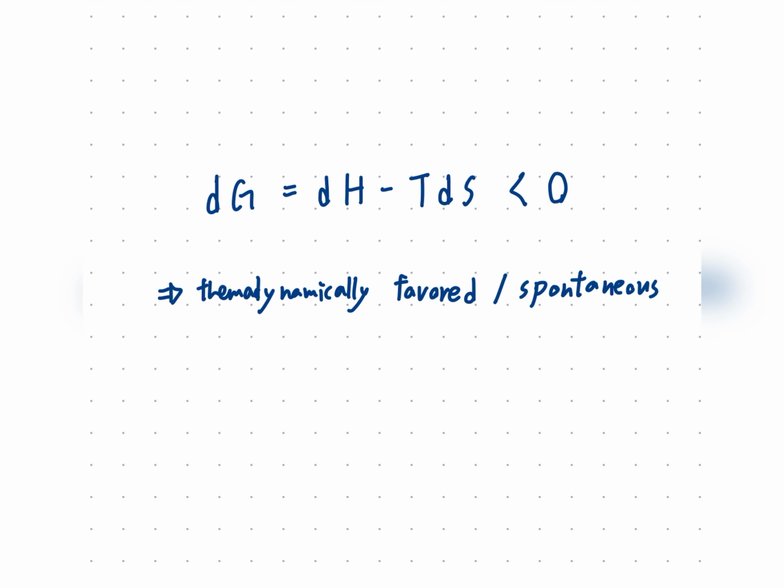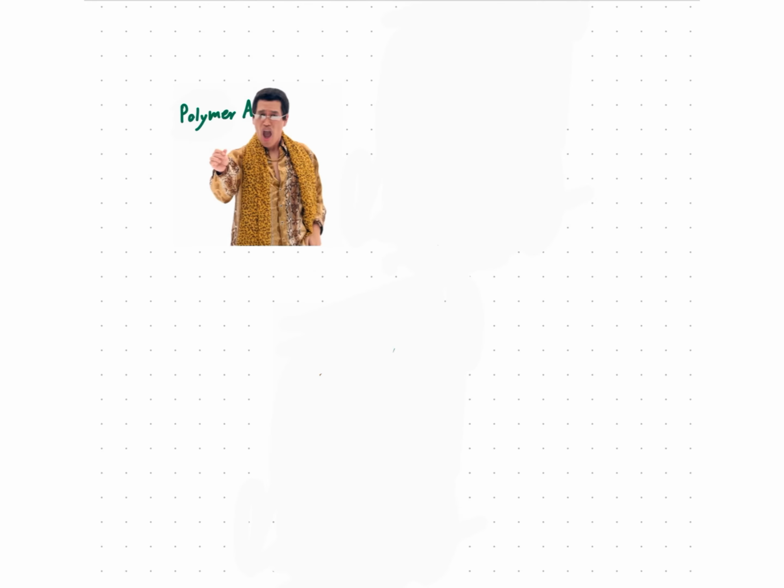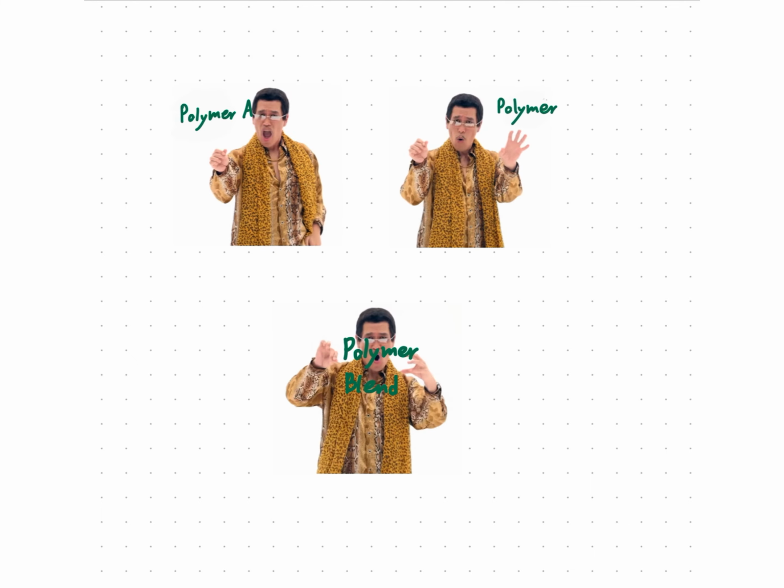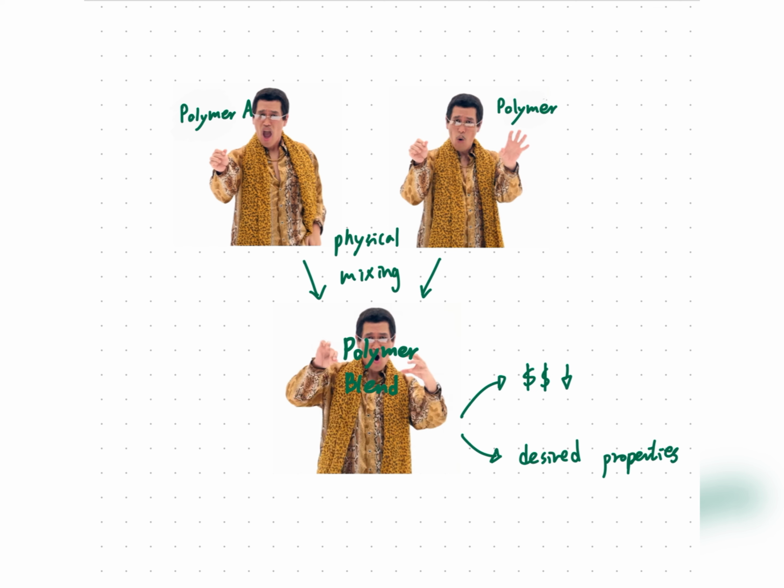One example of utilizing the Gibbs free energy consideration is to determine the miscibility of polymer blends by predicting the polymer's phase separation. Polymer blends are physical, but not chemical, mixtures of two or more structurally different polymers or copolymers, which are mixed when they're in the molten state. You may be wondering why. Well, by doing so, production costs can be reduced and tailored mechanical properties can be obtained, which means the blending can give rise to properties that are not deliverable by its constituent polymers.